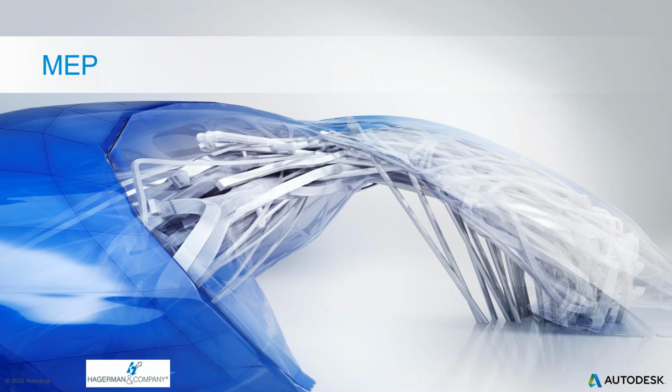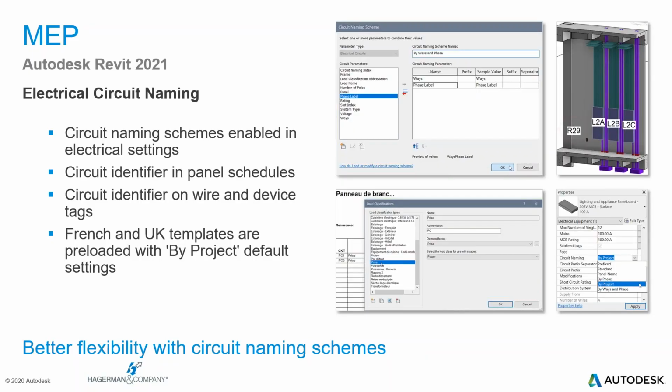Okay, so now let's go ahead and take a look at the MEP enhancements for Revit 2021. In electrical settings, there is a new node called circuit naming. The circuit naming schemes created here show up as options in the circuit naming parameter list on each panel.